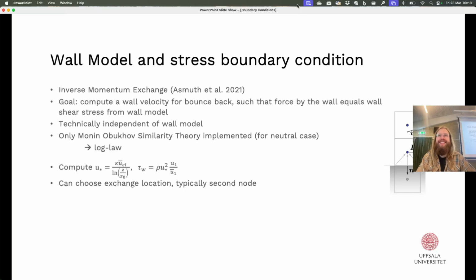Yes? You said it turned out it was better to do the time averaging. What happens if you don't do it? If you don't average at all, then you have to ask Henrik. I think if you don't average at all, you have this velocity mismatch, log layer mismatch at the first node of the wall, and this temporal averaging reduces the log layer mismatch.